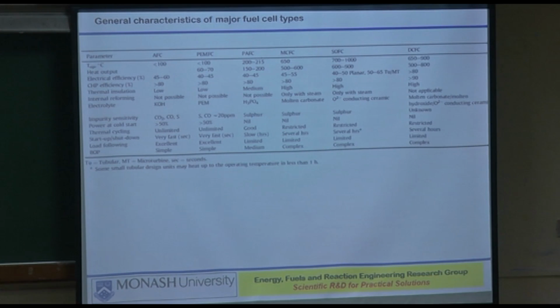The problem is that to maintain the sealing for the planar thing, as we were discussing, having a square cross section or rectangular other than circular cross section in a high temperature environment, the sealing is a big problem. So that has limited to some extent the planar cells development. So if you're thinking of making a rectangular one, drop that idea. Run away from it.